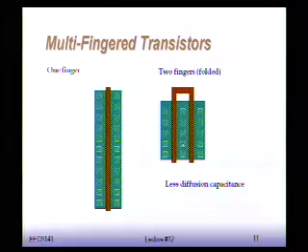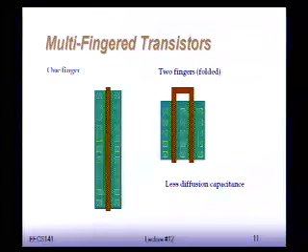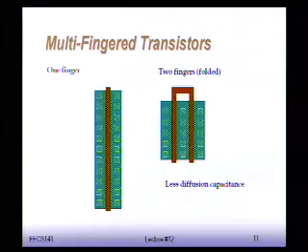What happens, though, is that now you have only 3 connections. And so these devices need to have either the drain or the source connected in common in order for you to be able to do this, okay? And you can imagine if you try to do it with 3 transistors, I think you would have 6 connections normally, and for each pair you lose 1, so you end up with 4 possible drain and sources, right? So you need now 2 nodes in common.